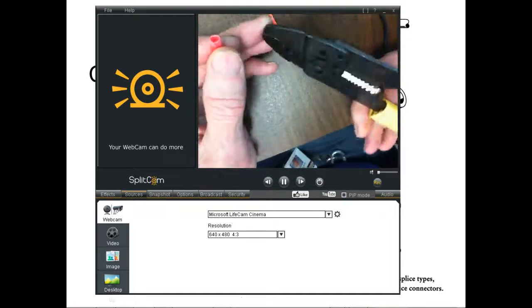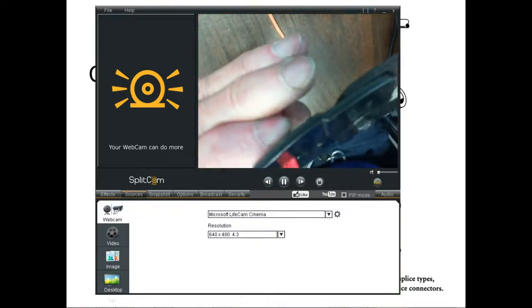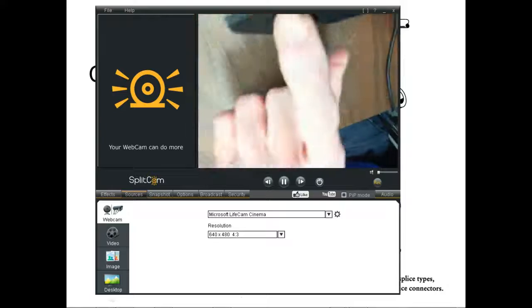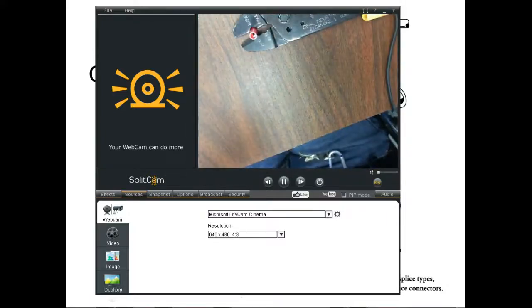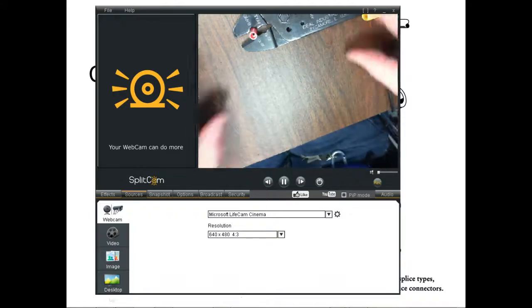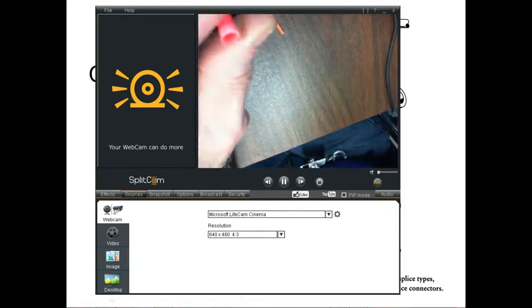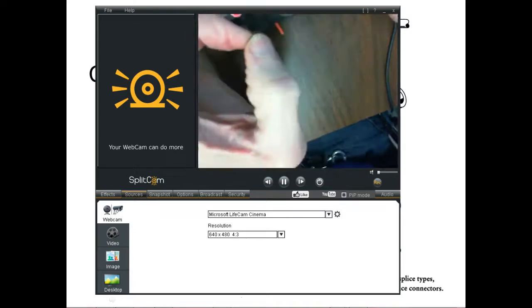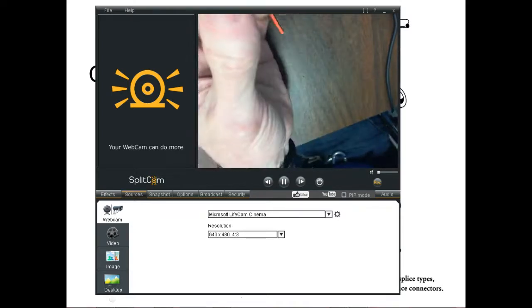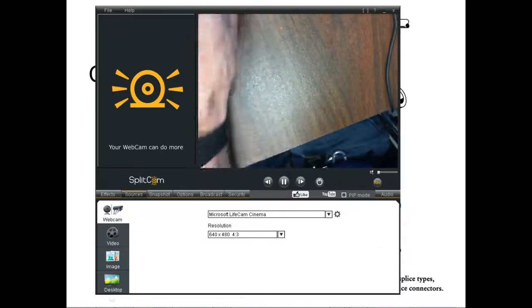You're going to have to strip these, and we'll give you the links on how to strip them. The first thing you do is find that notch in here. If you ever look, you see it's flattened out and it spreads apart. So we put the round side where it meshes right there, and crimp on the other side. Do you understand that? Charles, do you understand that?